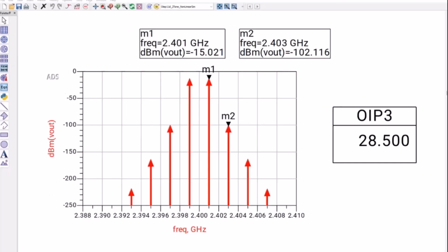Want to design such as a portable jammer? Not pretty sure about that question. I guess you might consider talking to your local Keysight team. Can you tell us how an inductor in the source affects gain at high frequency? I would never recommend having an inductor in source degeneration. If you're doing traditional RF microwave design, if you're doing RFIC, it might be okay, but definitely not in PCB. It will give you headaches at high frequency. It will cause serious oscillations at high frequency.